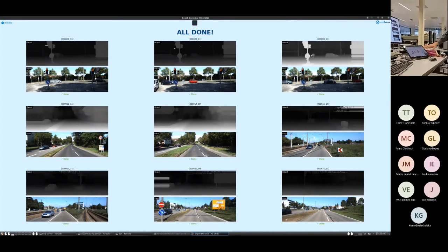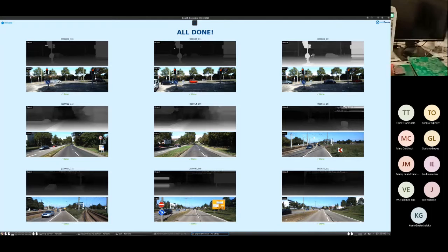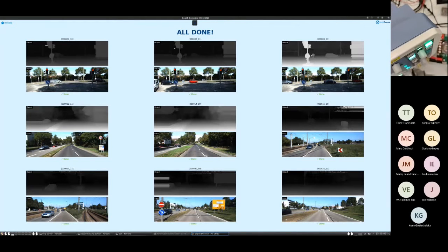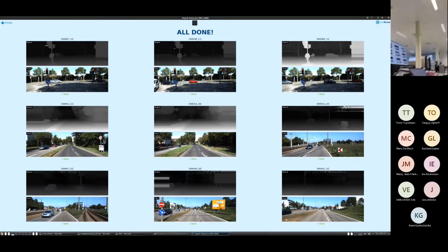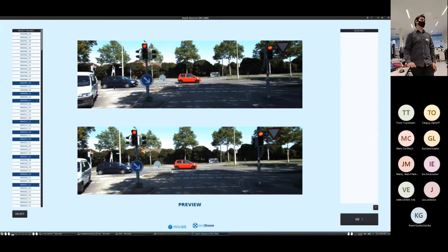But that would also translate into about 6 times higher latency because we're limited by this I/O, and also a much higher energy because right now this I/O is using about half of the energy of the actual processing. So if you do 4 times 6, your energy also blows up. That is why it's important to do this depth first, and that's why we have this chip that does depth first processing to stay very low on this I/O, and thus also on the energy consumption. Yeah, that's it. If you want, we can mess around with it. If we're honest, it's just going to look the same with others.